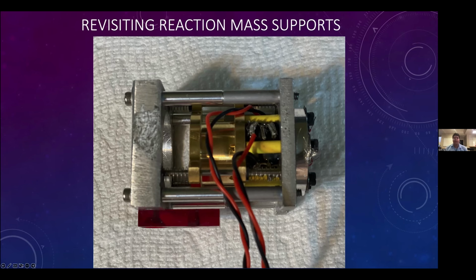where the bearings are. What that does is it gives the bearings, there's something called a 2-to-1 rule, where depending on the distance between bearings, your forces have to be on axis within a certain angle. You can think of it that way.